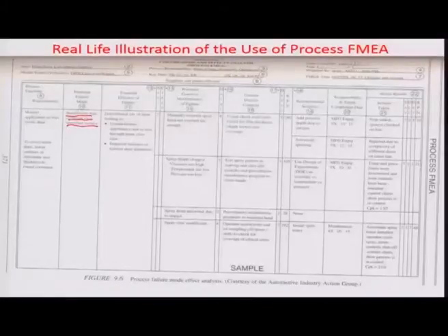properly, if the wax layer thickness or the viscosity, or let's say the application points are not as per the specified limits, there may be always a problem of holes getting uncovered, and because of which waterlogging may start taking place. So the FMEA process that we want to develop is to sort of study the wax application in a more appropriate manner within the inside of a door, so that this problem of corrosion can be retarded, and the potential